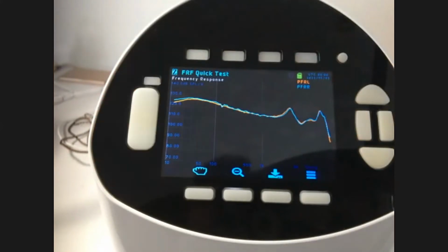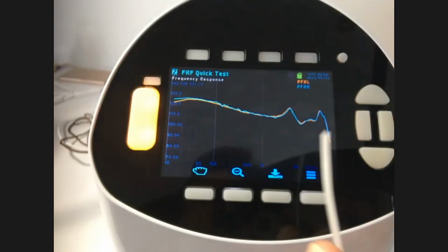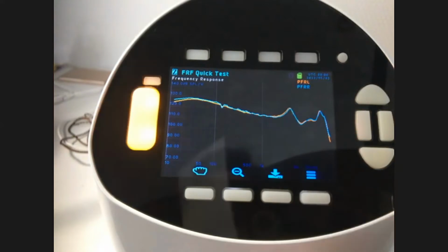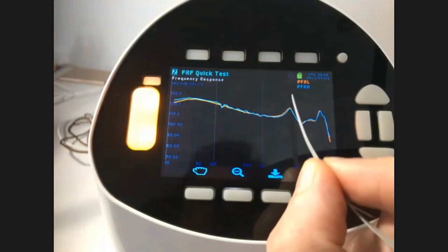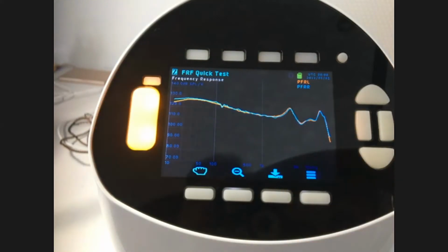It's a wavelength question. But for most insert earphones in a human ear, you'd be around the 3 or 4 kilohertz range. Okay. So you have this one resonance peak, and you'll see that over and over again, especially for insert earphones, where you've got that tube with a vibration at one end. So you've got a very clean tube resonance. Right. So that's a standing wave.